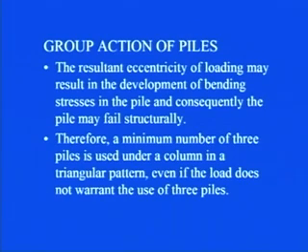Let us say that 100 kilonewton, or maybe even higher, let us say 250 kilonewton, is the load carrying capacity of a pile, and the load which is coming from the superstructure is 200 kilonewton only. So, as far as the loading point of view is concerned, there is no need to go for more than one pile. But from the consideration that there should not be any eccentricity present in the foundation system, 3 piles are provided.